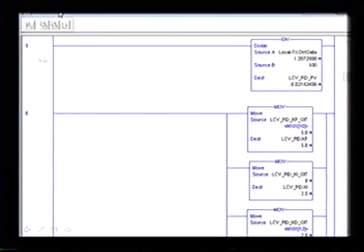Okay, so next thing I do is I have a divide. The reason I divide here is I just want to get this value into a proper unit, let's say if the input card comes in with a different unit, or if there's some division I need to do, I'll just do it here. A lot of times I just put 1 here, and it does nothing. All it does is take that value and stick it into the level control process variable. So this is actually the tank level, right? The actual level control valve in this case, and I multiply it times 100 and put it into the process variable.